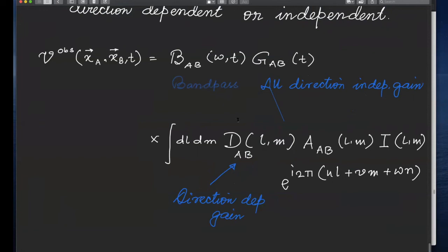That is not obvious from the equations of signal to noise ratio which you wrote, because that is only dependent on the system temperature, which is calibrated for one interferometer. But the signal to noise ratio also depends on the method which we used for the calibration, and it is very important for H1 observation that the signal is very weak. So is there a different approach we need to take for H1 observation compared to what we usually take?